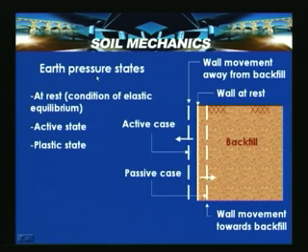So, among the earth pressure states, we define the at rest condition, that is a condition of elastic equilibrium, where the wall is at rest, that is no movement, a zero strain condition, which is next to impossible to maintain. So the possibility of the active and passive states is always there.